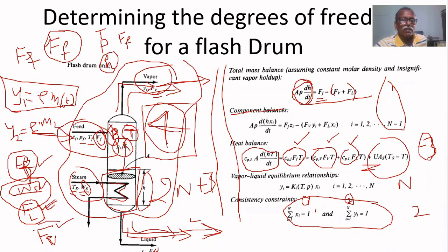In the same way, FE also we can see. If more vapor is taken out, if you increase the vapor flow rate, definitely there will be a decrease in pressure. Temperature will increase. So pressure decreases, temperature increases, when you take more vapor.